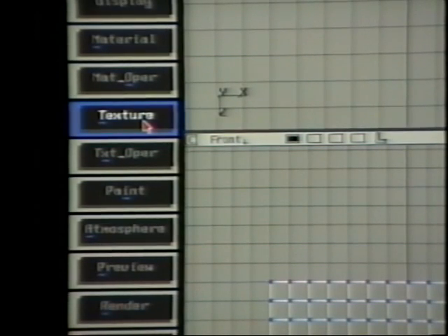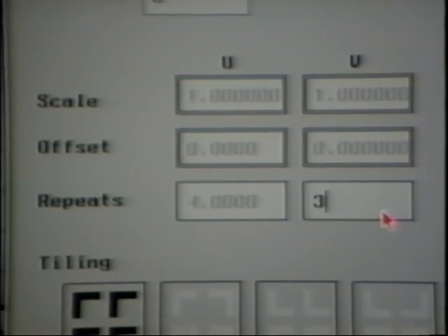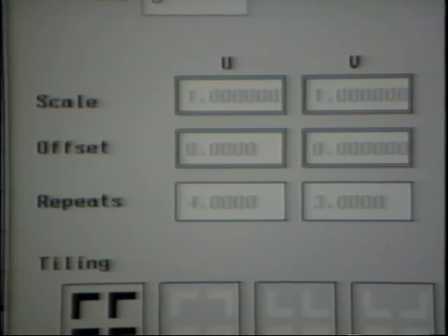We've been relying a lot on using multiple repeats of our maps across each textured surface. This isn't something you want to do with just any image. If we took a picture that wasn't specifically processed as a tiling texture map and applied it with a number of repetitions, we would see visible seams, edges to each repetition of the map in our rendering.